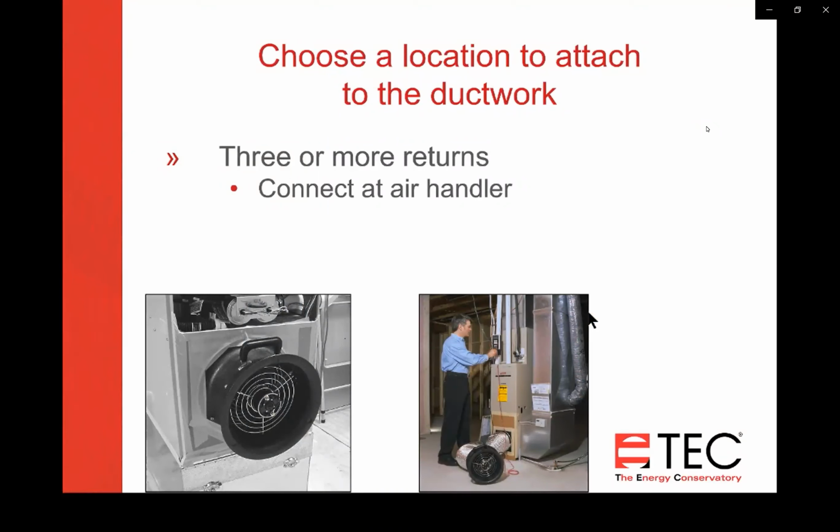Next, you want to choose a location where you're going to attach the fan to the ductwork. If you have 3 or more returns, you want to connect at the air handler. And if you're doing a pressurization test, you have the option of using the flex duct or not. You can get more airflow, and maybe it's easier, maybe not, to connect up to the air handler without the flex duct, but you have that option.